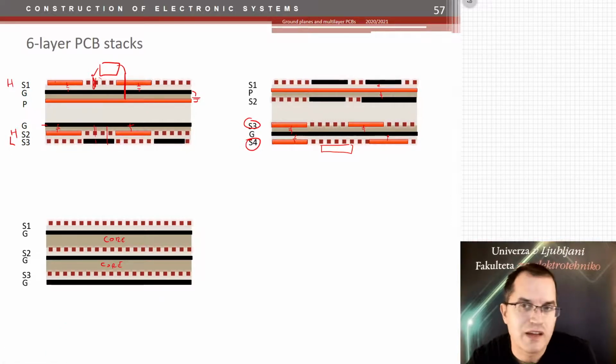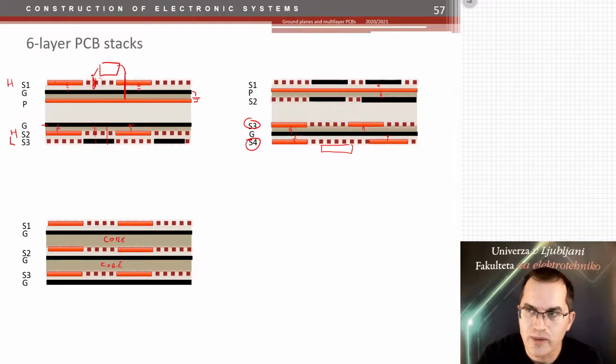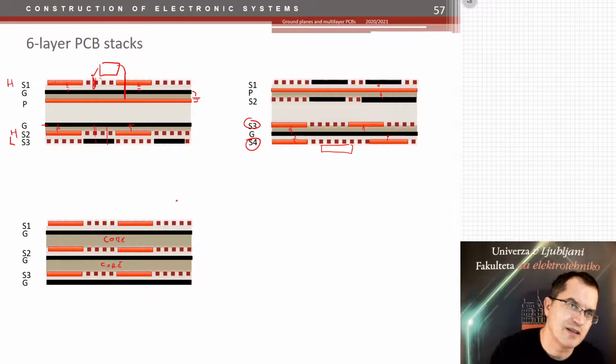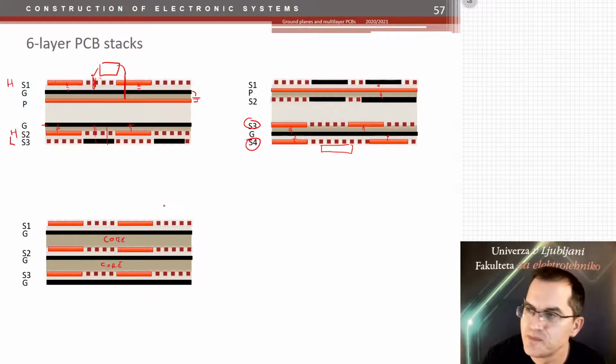So you have to provide some power, and of course you do it by providing, whenever possible, power layers on all signal layers. And then you have nice capacitances between power and ground. And